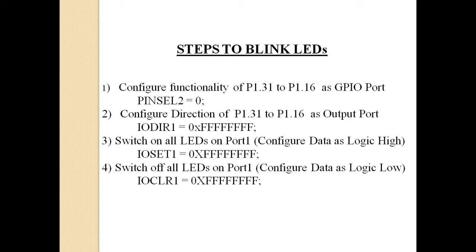Here in LPC, all the ARM based microcontrollers, VCC is 3.3 volt. You need to keep it in mind. Most of the other microcontrollers like Arduino, Atmel, PIC, etc., they are operating on 5 volt VCC, but ARM based microcontrollers will be operating on 3.3 volt VCC, right?